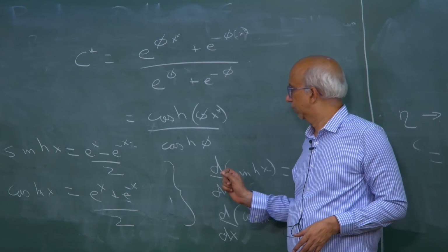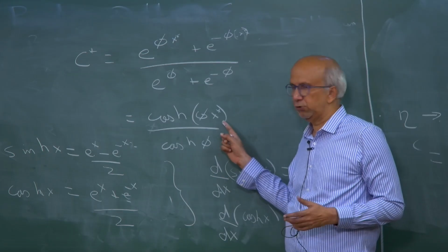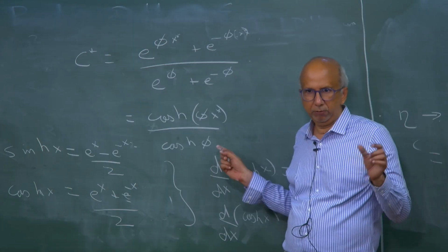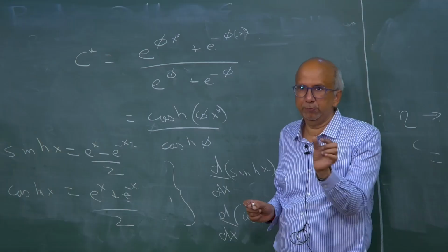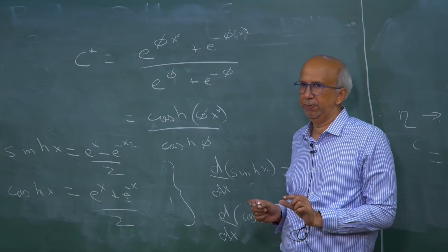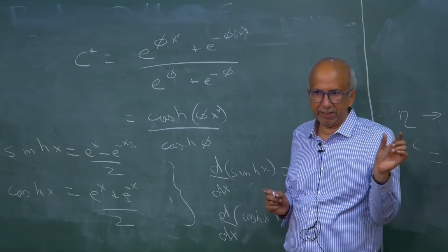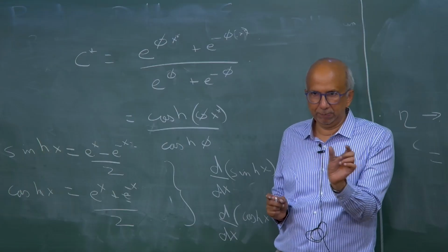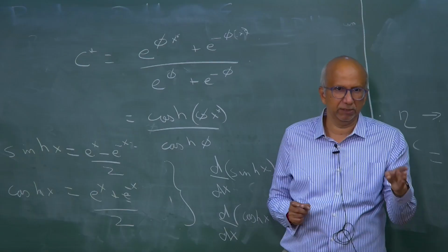When you use the actual profile, with the internal diffusion resistance, the reaction rate at different points is going to be different because the concentration is different. The reaction rate you calculate in the pellet varies from one point to another.